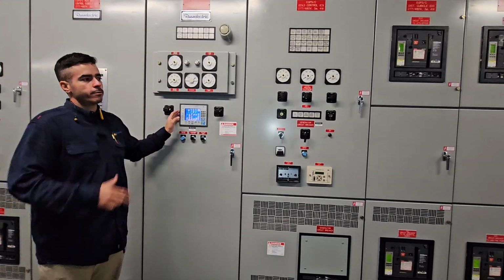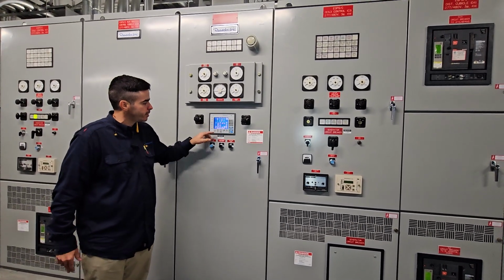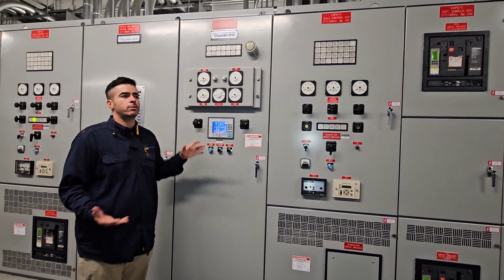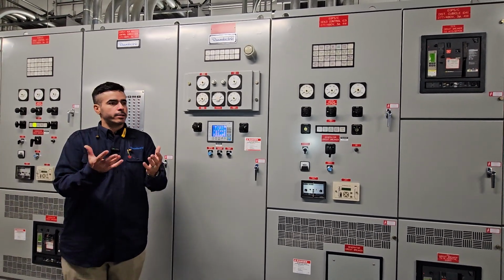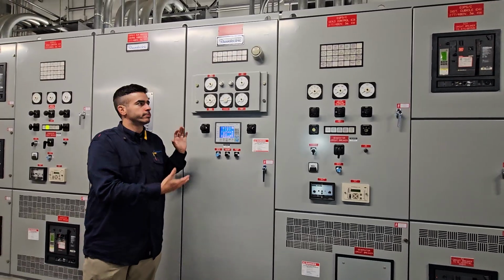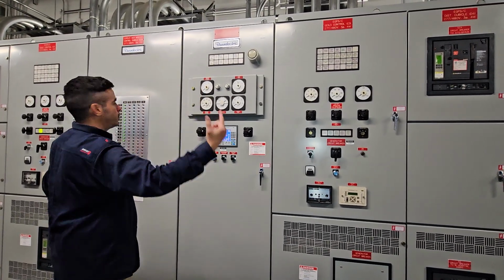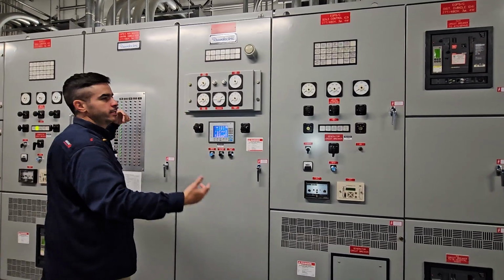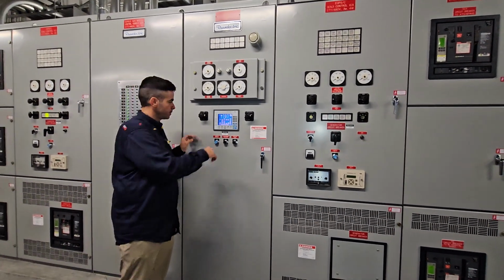Okay, so for those that don't know, the system also has some features here that allow you to do a no-load test. No-load test means nothing's going to transfer. It's just automatically going to bring both generators online. Basically what he did right now, it's going to do on its own, right? So I'm going to hit that button so you guys see how this starts, one hits the bus, the other one syncs, and then it's good to go, and then we end the test, okay?